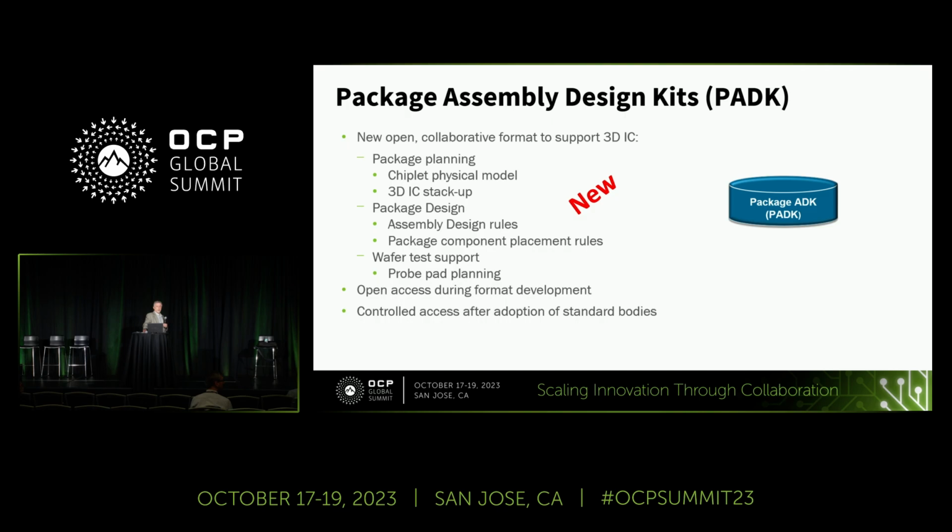And then the other category kind of falls into package design, assembly design rules. So these are the rules on how this interconnect is going, spacing, width, that type of information. And then there are some higher level rules that may be more related to the package. So things like spacing to cavities and such like that.